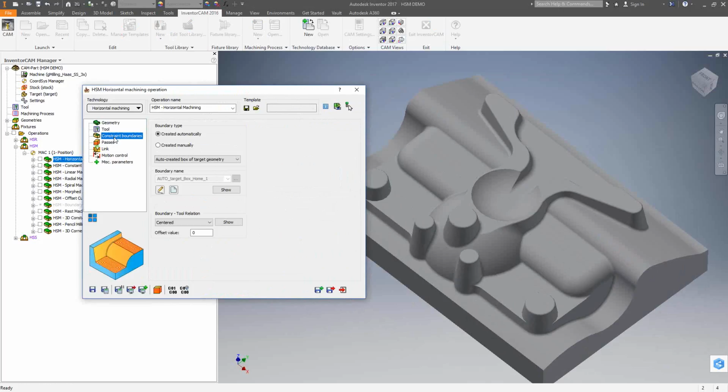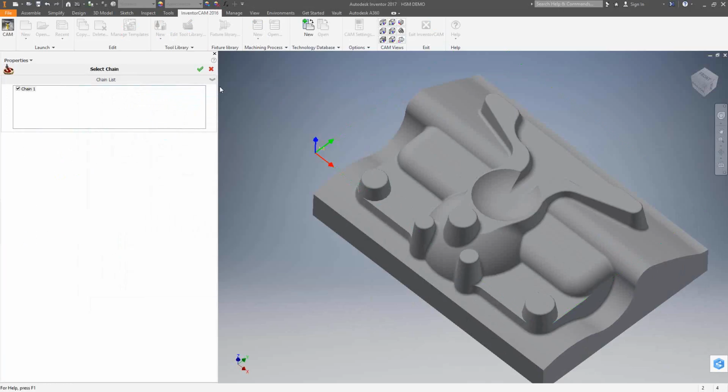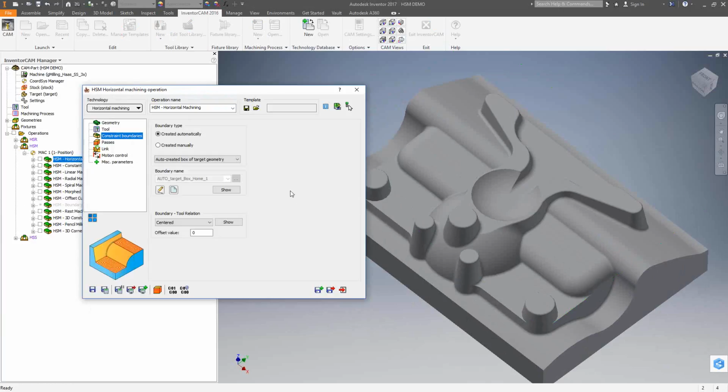That being said, you can use the constraint boundaries to limit the travel of the tool. The constraint boundary with the machining options allows you to make a really good finishing toolpath for different areas of your part. For this video, I've just used the automatically selected boundary of the entire part. What we'll see here is how the different options apply to the overall part, and we can also get an idea as to how they may not fit certain areas. Again, the geometry that you choose is just the target. You use the constraint boundaries to limit the travel of the tool, and you choose the technology options up here to use the best toolpath for the selection of the geometry with the boundary area.